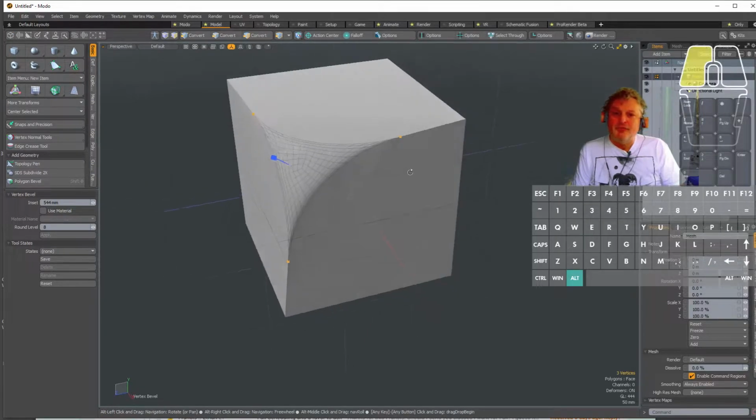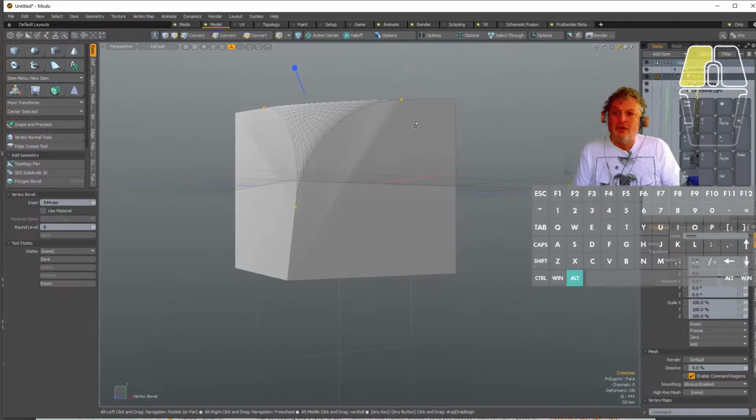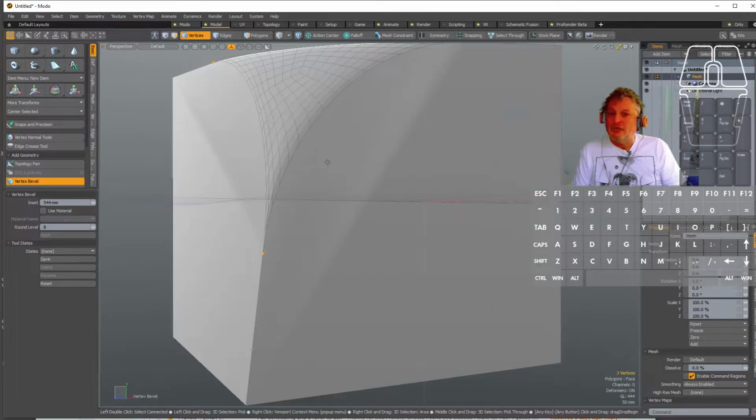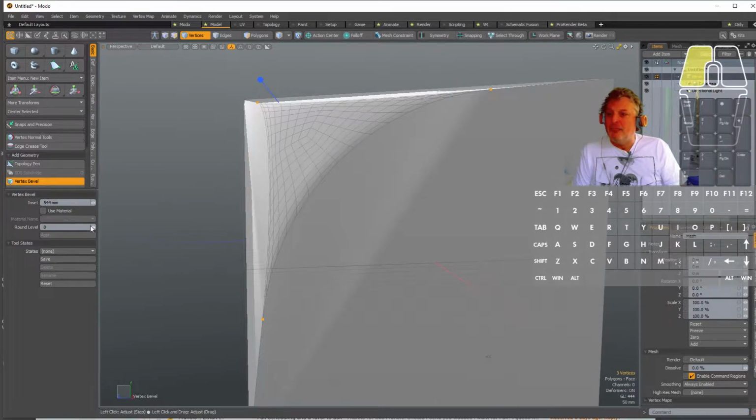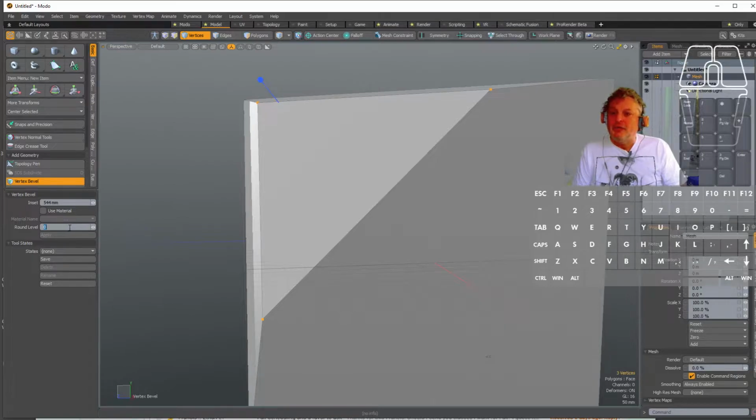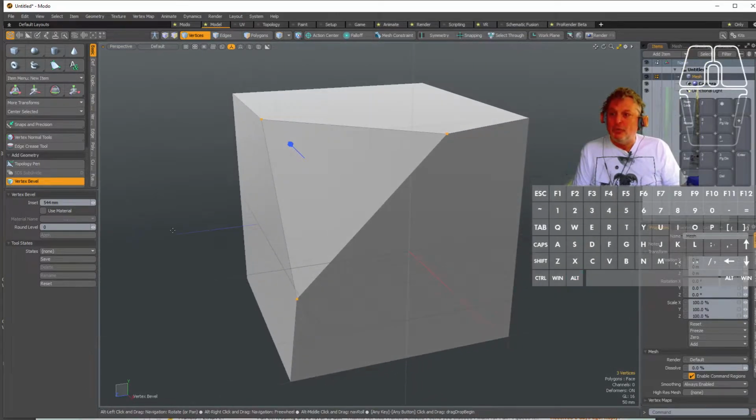As you see, these subdivision techniques always head towards a curved shape. It's still a matter of straight lines. It's just how many I'm putting in and how much they're going to approximate a curved shape. That's a level of 0 where it makes just 3 new points. I can enter these. I'm going to put a 1 in there.